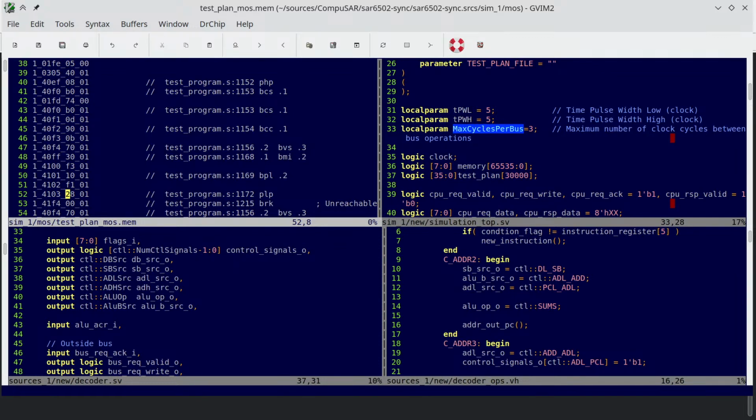The problem, however, is that this decrease needs to update the program counter high. So we're at 4102, and we need to jump back, I think that's 14 values, to 40F4. But if we update only the program counter low, we're going to get 41F4, which is indeed a read that the 6502 does. It actually reads from there, it just never uses that value.